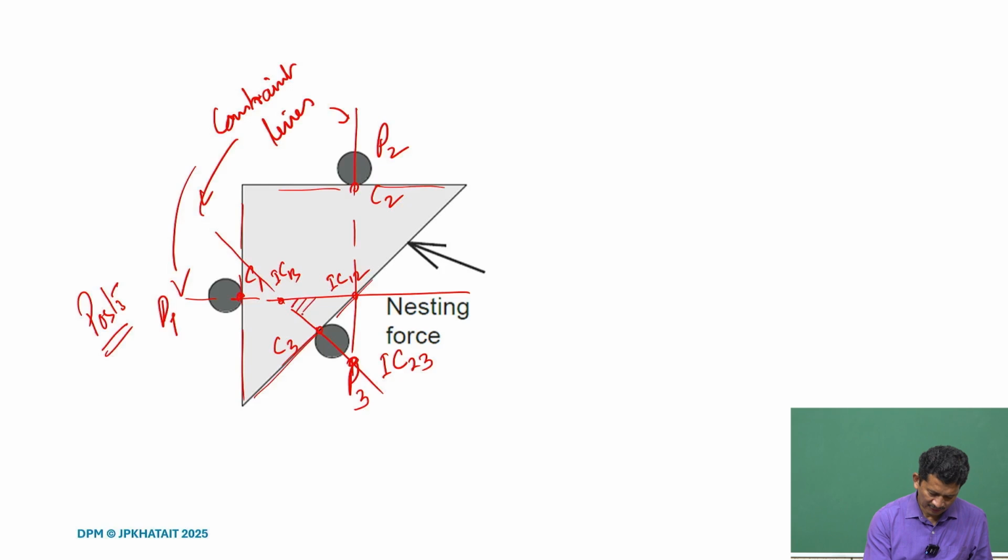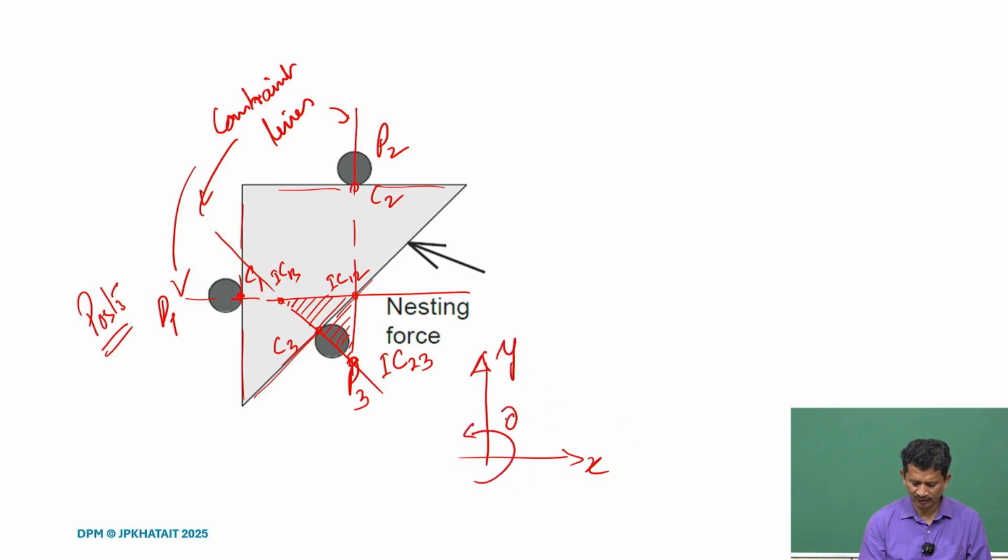But we also realize that if we extend the constraint lines, and if they enclose an area, if it forms some kind of triangle, what we can prove and easily see is that there is no over constraint and the system is exactly constrained. So, in this case also, if we analyze, we find x, y and theta z all constrained.